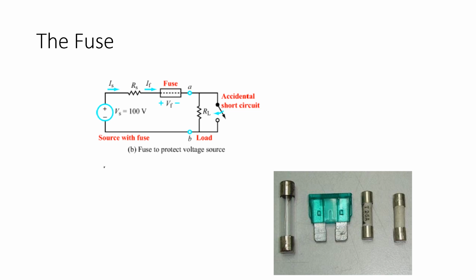So another example is, and don't do this, never ever do this, but theoretically, if you took a hair dryer and you plugged it in and it was going on and then you dumped it in the bathtub, if you had no fuse in there or no circuit breaker, the wall power would continually dump electricity into that hair dryer, and you'd have a short circuit in there because the water would get in between the two resistive elements, and you would just be essentially dumping a whole bunch of current through that water, and you're actually going to create electrolysis, and you're going to break those individual water molecules up into their hydrogen and oxygen molecules, and you can get a whole bunch of different problems with this, including one, if you touch the water, there's a chance you can get electrocuted if you're grounding well.